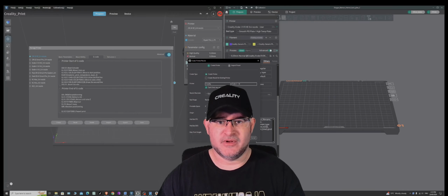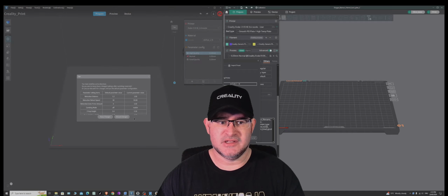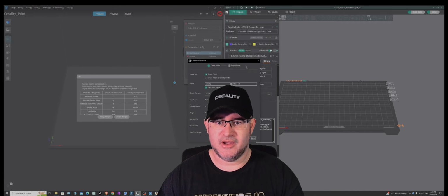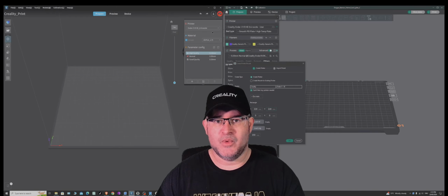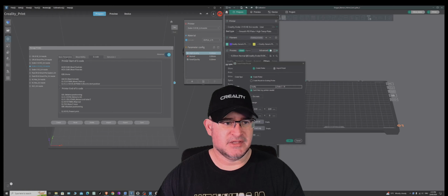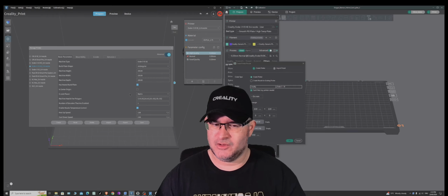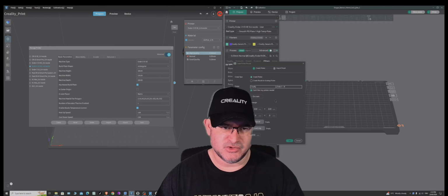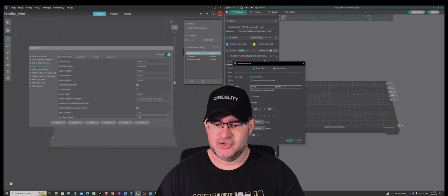And once again, I'll just get rid of this real quickly so we can bring this up. So if you want to go into comparison, you can simply bring it up from there like so. And we can go to Ender 3 V3 SE there, click manage, and we can see our basic parameters right there. So if you're not sure and you just want to copy it straight across without looking at your printer build volume profiles, you can do that as well. It's another cheap way of doing it. So anyway, go back to it, 220 by 220, and then our build height volume is 250.